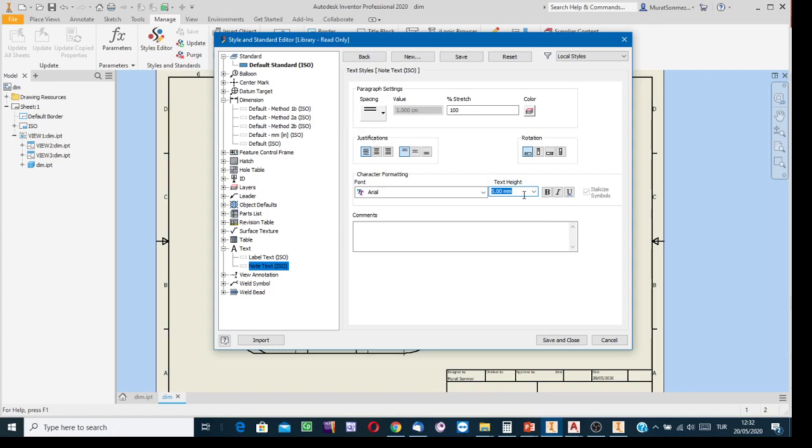In AutoCAD, in such a box, it is a must to write the recommended font height times the inverse of the scale factor. But in Inventor, directly write the font height, because Inventor is new generation software and does not apply the scale factor on the text or numerals.